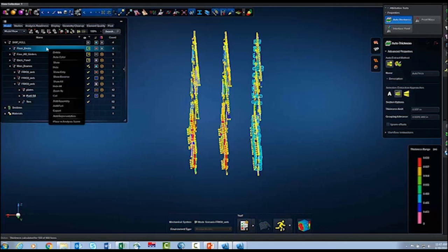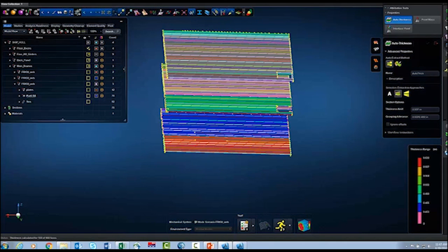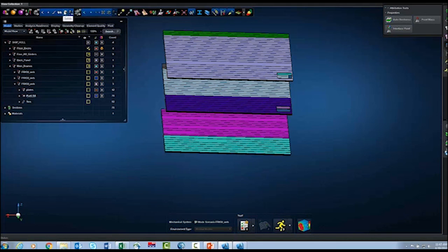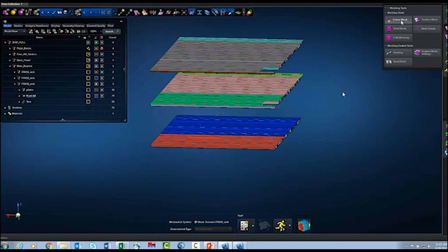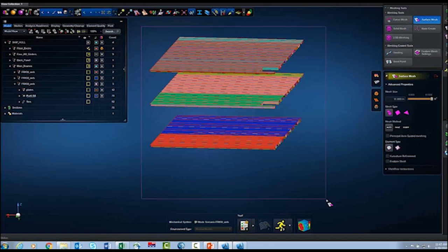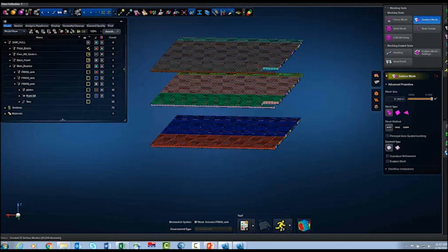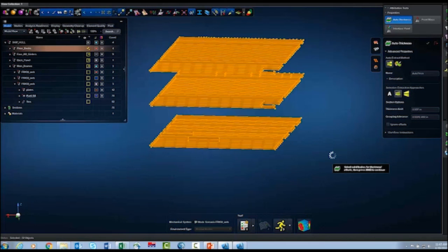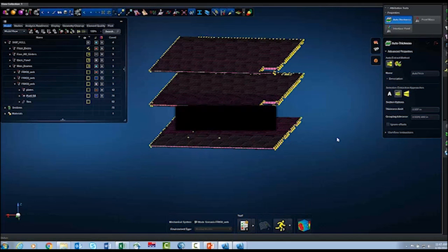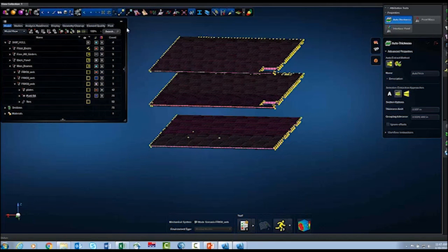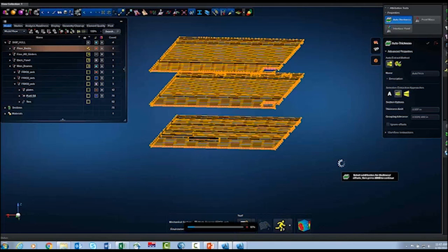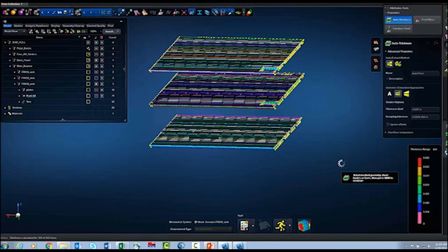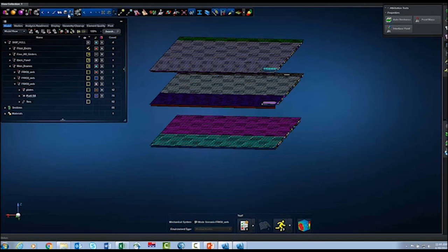Let's go and do the floor decks real quick. So we'll show those only. Let's hide the solid real quick, and let's mesh this. So we'll create a surface mesh here. I'll use that 11-inch mesh size. Let's assign the thickness real quick. Oops, got to pick my solids. Keep in mind that I could do an incremental solution on this. In this particular case, in the interest of time, I'm not doing that, but I could actually be running the floor panels. I could be running individual frames just to kind of verify and validate those.